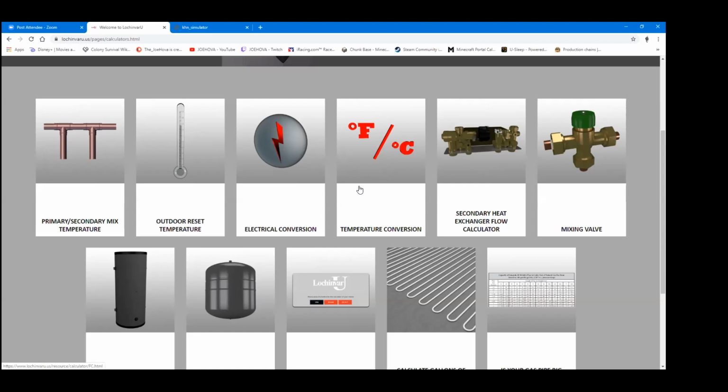One of the things that we struggle with, especially in cold environments like you, is the amount of glycol we find in systems. When it comes to fire tube boilers, water chemistry is critical. I think you all understand that. And way more critical than it ever was on water tube. For many, many years, Lochinvar was a water tube company. We preached lime scale free performance through flow and velocity and things like that. And that's still true with all of our water tubes. But when you get to a fire tube, you don't have any control of the velocity through that heat exchanger. It's basically a big bucket. So water chemistry becomes absolutely critical.